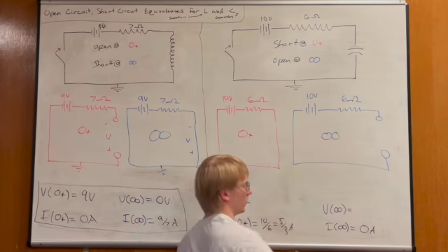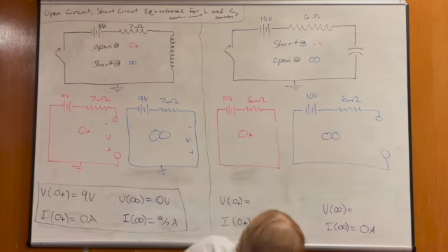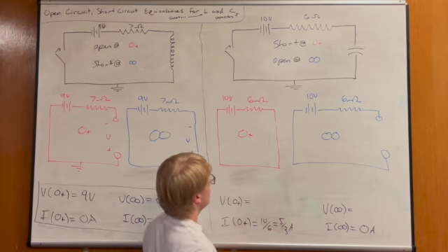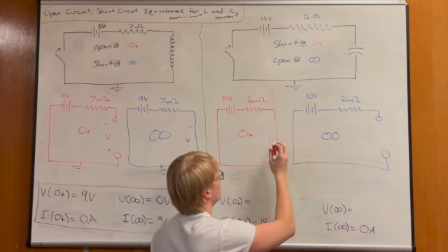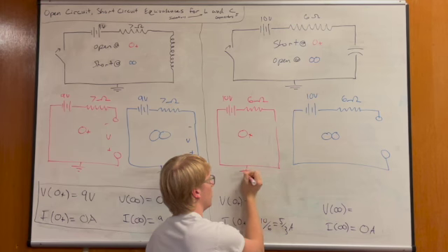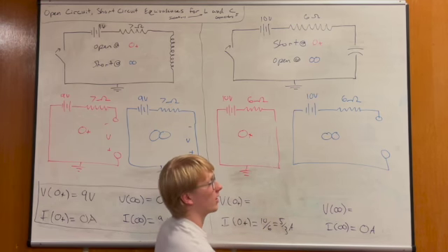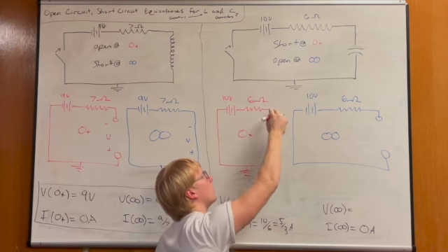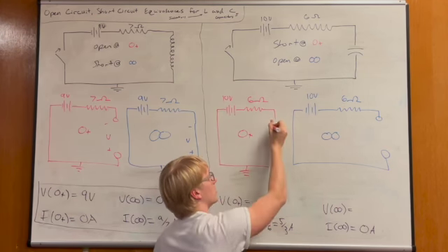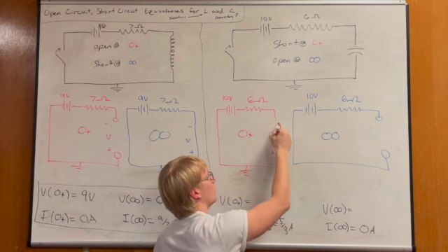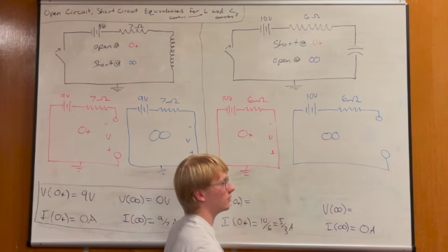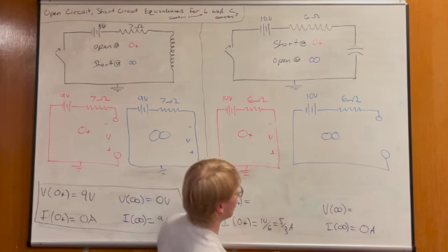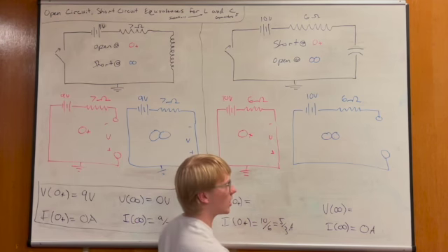So now we can look at the voltage jumps. This is ground, so we can make it whatever we want. Typically, we're going to make it 0. So this entire node is 0, which means the voltage jump from here to here, there is no jump. No matter what this node is, it's the same node, so it's 0.